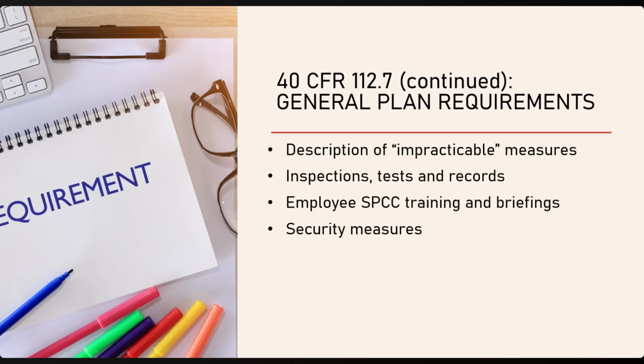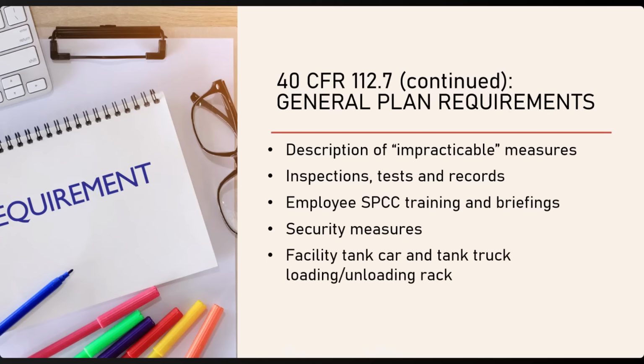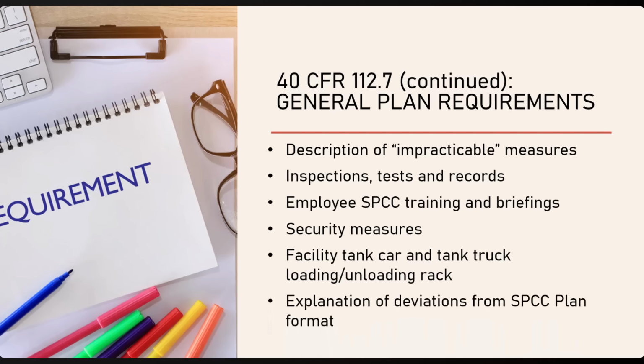Security measures should be described, with the focus being on how you secure and control access to the oil handling, processing, and storage areas. Measures for preventing spills from facility tank cars and tank loading and unloading areas must also be described. In addition, the procedure for inspecting a tank truck for leaks before its departure must be included. Lastly, if your plan deviates from the SPCC Plan list of topics covered here, you must note the deviation so that it is clear that all required contents of the SPCC Plan can be easily located.